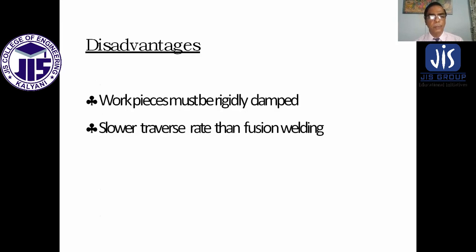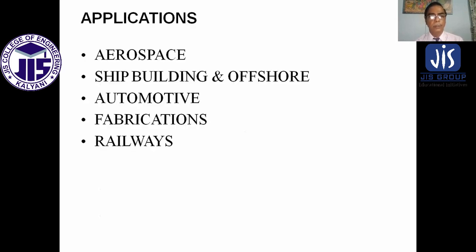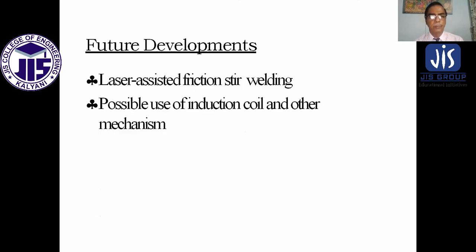Disadvantages: workpieces must be rigidly clamped, slower traverse rate than fusion welding. Applications: aerospace, shipbuilding and offshore, automotive, fabrication, railways.